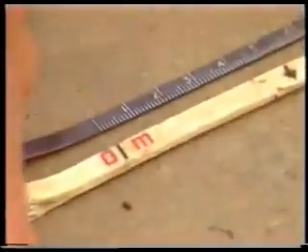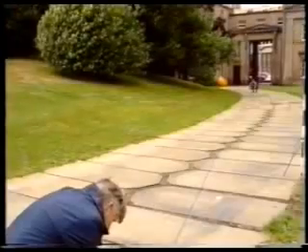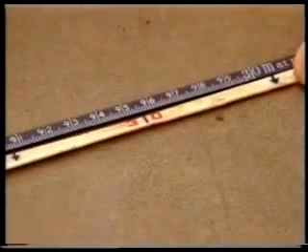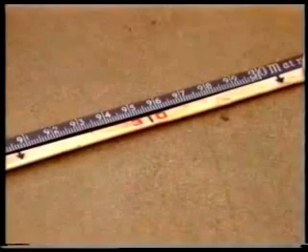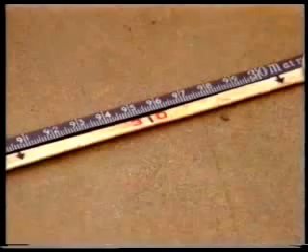Measurement takes place on a flat, smooth surface both before and after survey work. The mean of the 2 measurements gives the standardized length of the tape or chain. This is used to calculate a standardization correction to be applied to the measured length of the line.